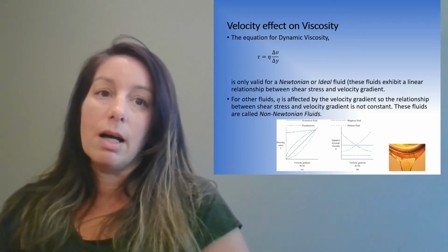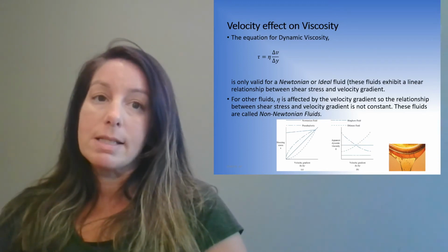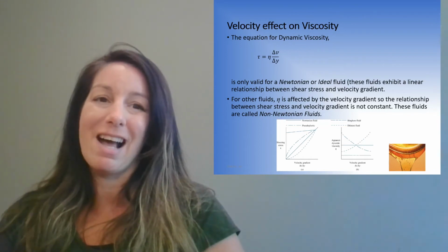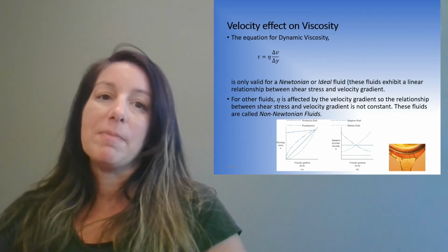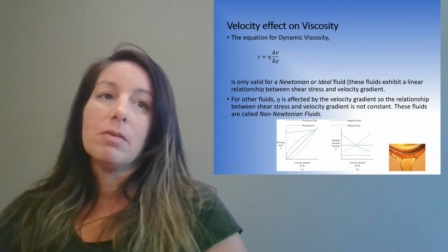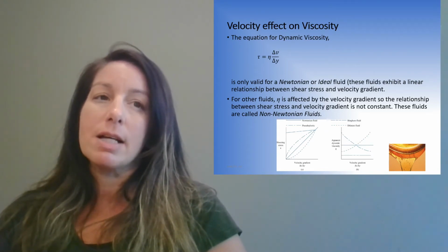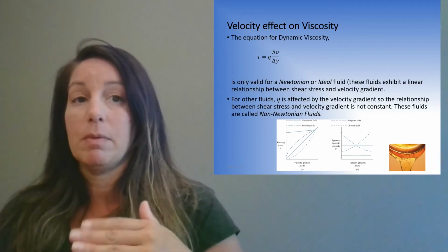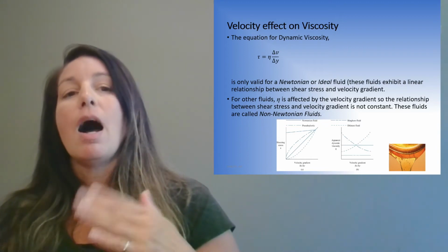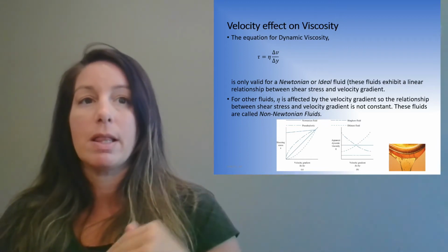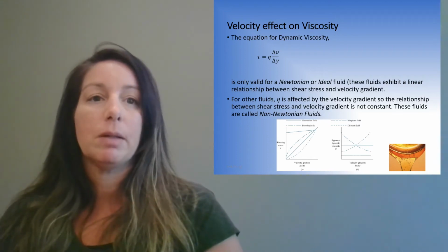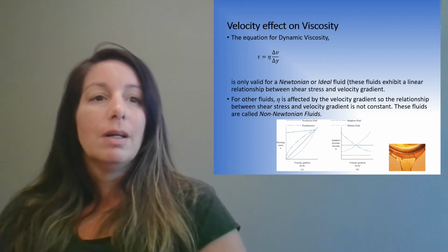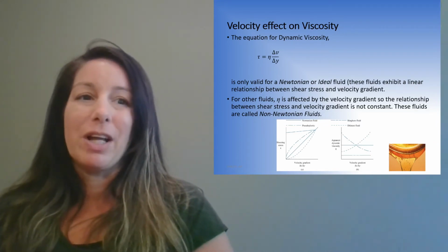We also have, let's see now, what's our next one? Pseudoplastic. We'll get into this, don't worry. Just looking at the figures now. The shear stress and velocity gradient is a little bit different in shape than the Newtonian. You can see it's above the Newtonian fluid, this linear relationship. And then we've got the dilatant fluid, which is below the Newtonian gradient.